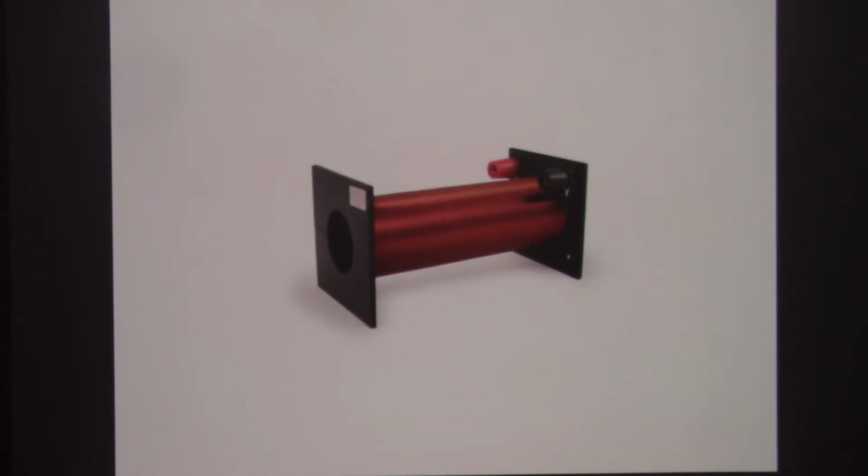Doorbells, for example, a lot of the ones that actually ring something, have a solenoid built inside, and when you hit the doorbell button, it turns on the solenoid and then releases, turns on and releases, and that solenoid pulls a little piece of iron into the bell and then releases it, pulls it in and releases it. So these show up in mechanical devices like that.